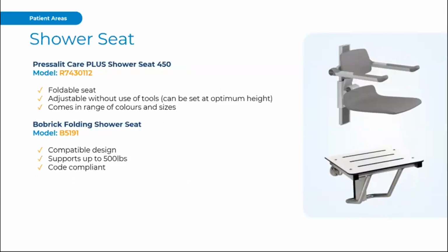Now, the key differentiating aspect of a long-term care shower area versus a typical shower area in, say, a community center or rec facility is the fact that the user often is having an assisted shower. The staff there will be assisting with the experience for safety and for cleanliness. And the BC and OBC simply call out the area must have a hinged seat other than a spring-loaded hinge seat, or a fixed seat that shall be not less than 450 millimeters wide and 400 millimeters deep while carrying a minimum load of 1.3 kilonewtons, 293 pounds.